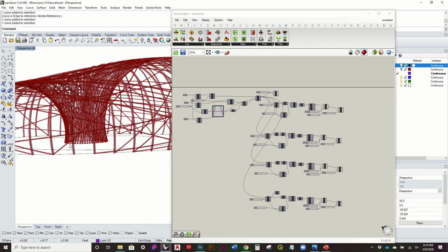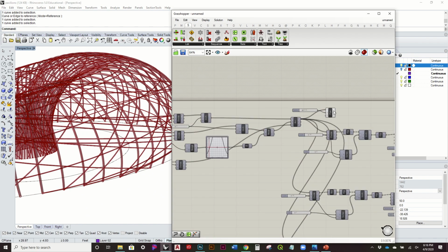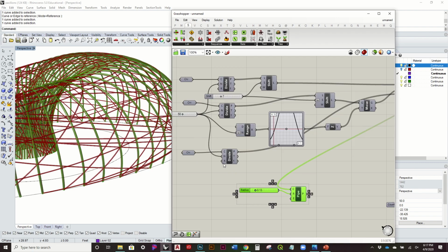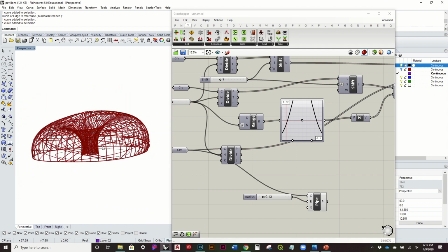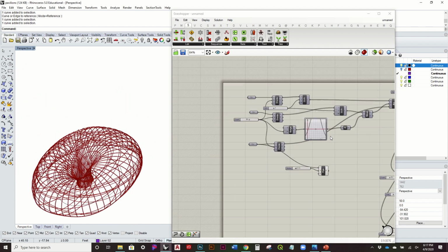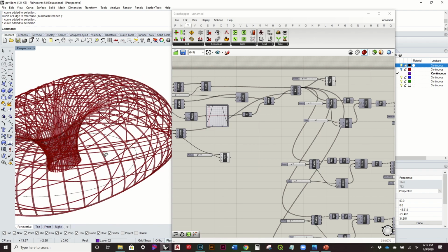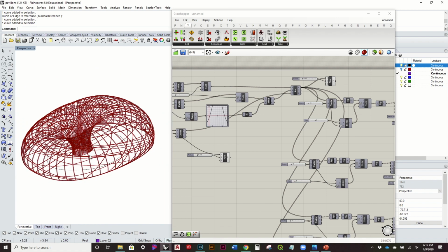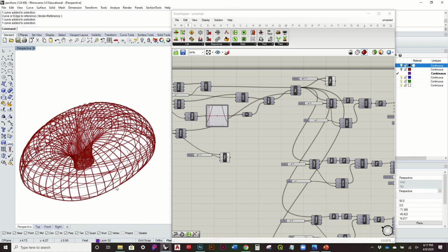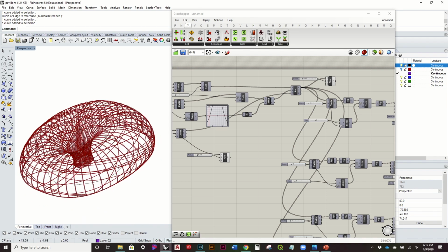If you really want that base curve, I would probably use the same thickness and just use it for this curve, right? So now I have a base. Once you get that, it'd probably be good to just bake these into their own respective layer, and then you can start to use a shape for your entryway and use the Boolean and trim it out that way. Then you can use that same curve as it intersects to cut it out.